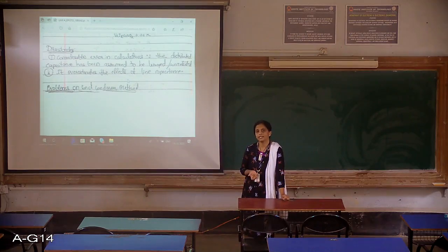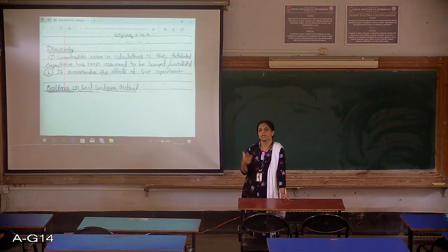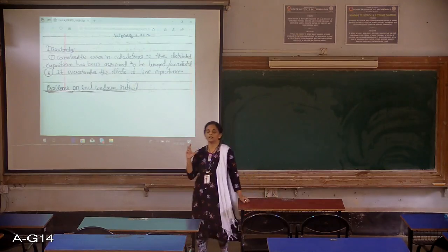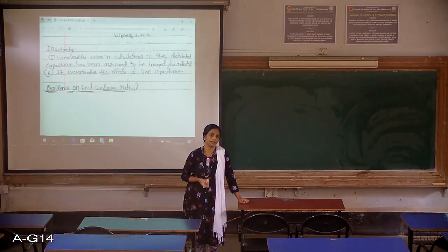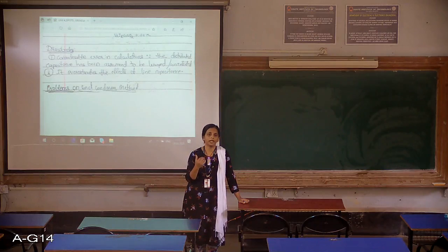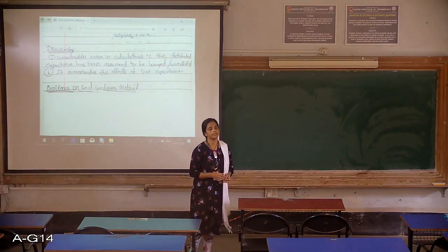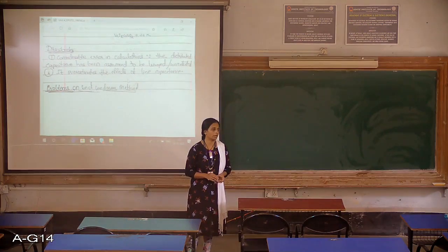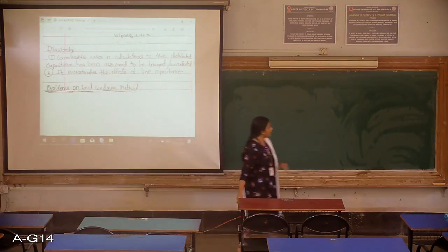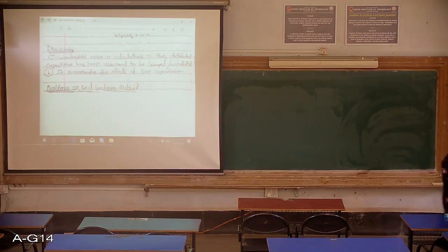In the end condenser method, R and L are considered as lumped parameters, and the entire capacitance of the line is assumed to be lumped at the far end of the line. Based on that, you saw the various phasor diagrams associated with it. I think we stopped there, and there is one problem to be taken up with the end condenser method. Then I will switch over to the T method and pi method. So we will take up a problem on the end condenser method now.